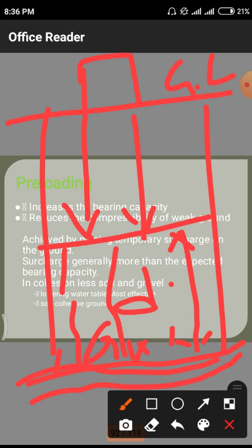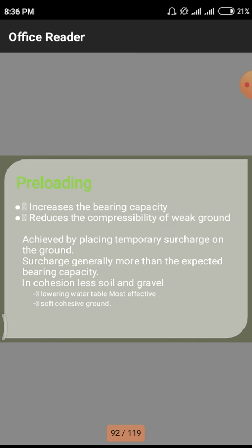Automatically the entrainment of water is there, and a huge amount of collapse and settlement will occur due to this entrainment of groundwater up to foundation level. So we need clear information at what depth groundwater is located, at what depth our foundation is, and how much distance is between those two points.